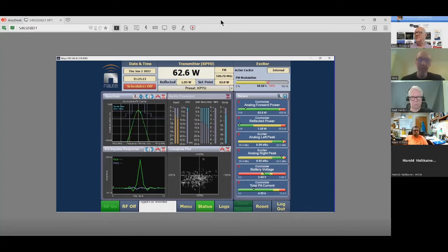And the spectrum we developed mostly around the HD operation and the third order intermod products that can really rise up if you don't have a well linearized system. But in the analog world, I don't think I've ever seen issues with the allowable mask that you've got there. So everything looks normal there to me.